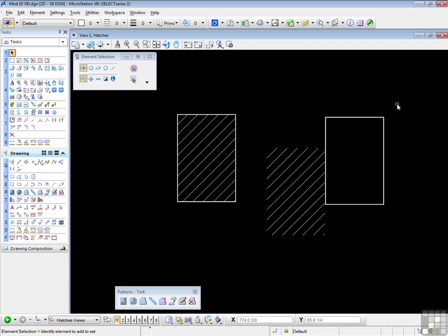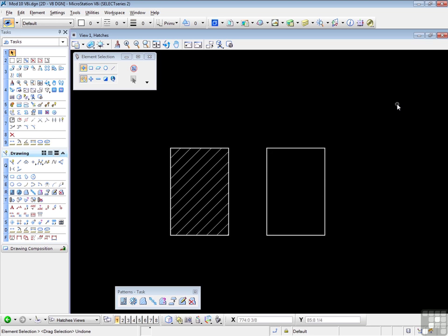Now again, this may or may not be what you want, although it is very useful to have the hatch take the shape of the edited element rather than having to redo that hatch. Let me undo those actions. Let me give you a little more information about the hatch lines that we can see. Clearly, since you can control the spacing value, it makes sense when, for example, you're designing a deck and you want to see the effects of placing 6-inch planks at different angles and starting point.